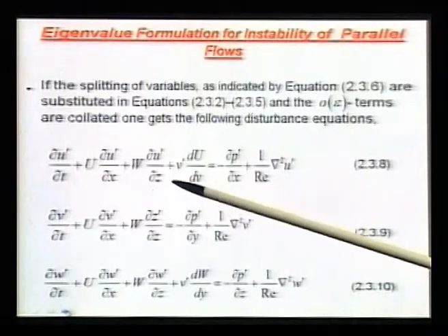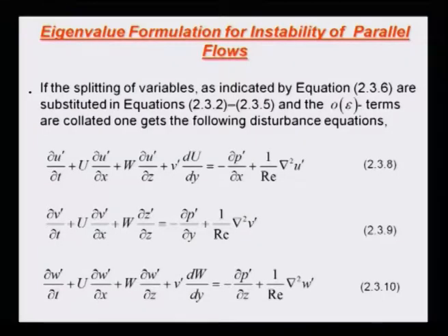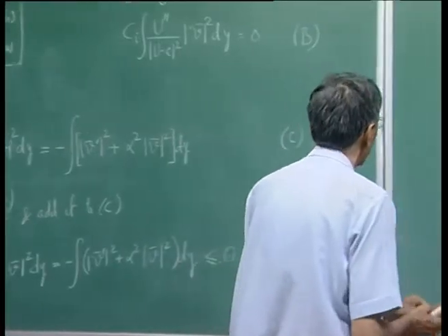You realize that this equation is written in non-dimensional form. That is why I have gotten the Reynolds number coming here, right. So, what you do is basically assume some kind of a length scale and some kind of a velocity scale and write down the Navier-Stokes equation in those terms.